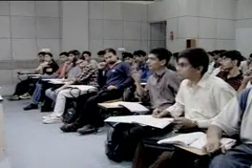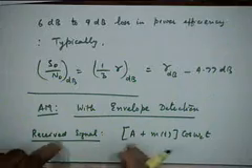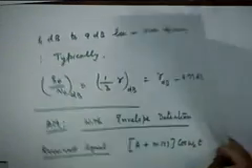So, if I write down a mathematical expression for the envelope in this case, that will be the amplitude only, A plus m(t). But that is not what you are going to receive. This is the received signal part. The actual received signal y_i(t) will have the signal part plus the noise part, and it is the envelope of the signal plus noise which will dictate the output. Is it clear? So, we need to look at that.